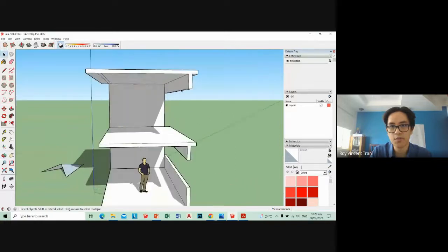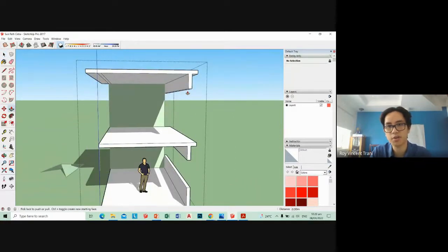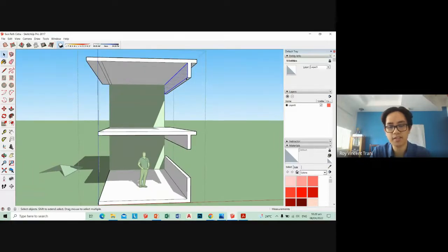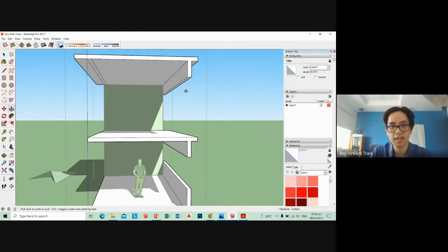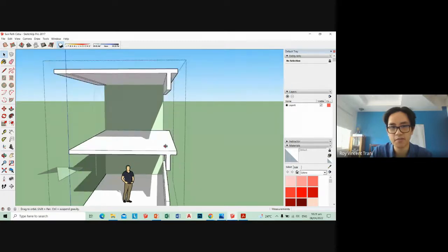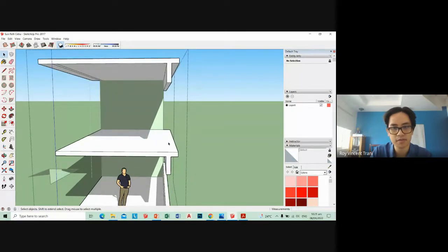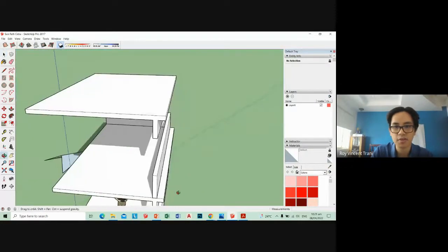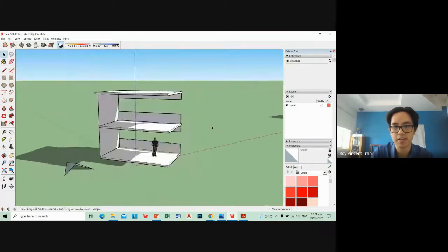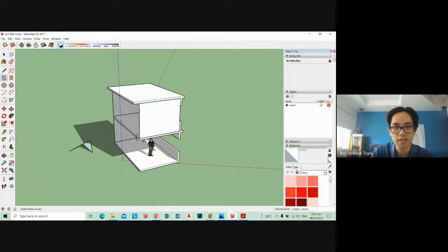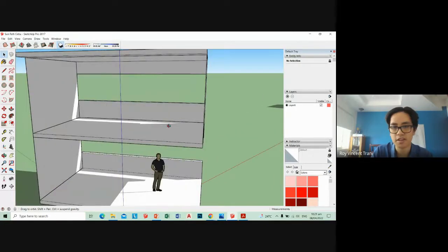So I think a better way, so you don't have to extend the eaves, is maybe to lower your window height. But that comes at the cost of reducing the visibility from the outside. You basically have no windows in December because a lot of sun is coming in. And maybe if you have something like this, and then you have it go up 0.9. It's not so much because the sun is coming in from the other end. Let's say you have a wall on this side of your building. The sun is a lot more manageable.